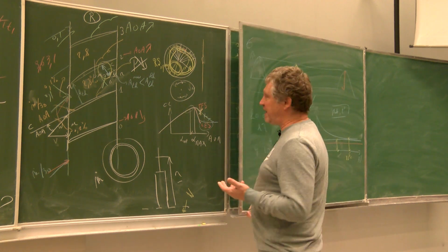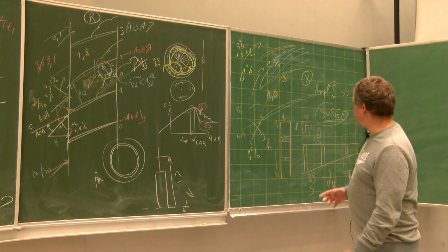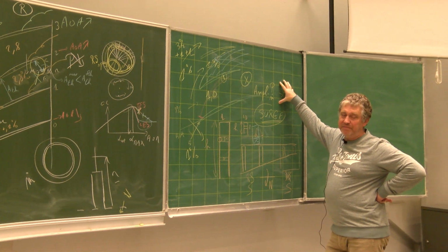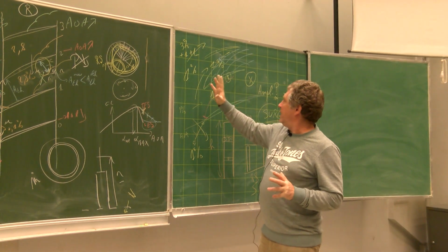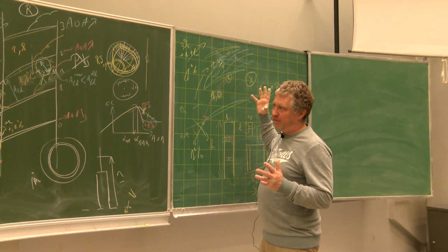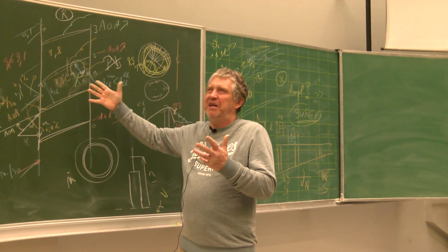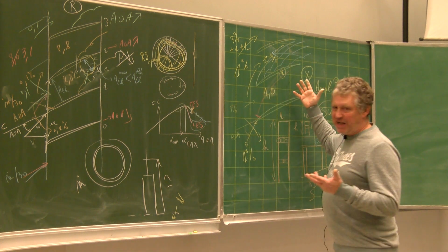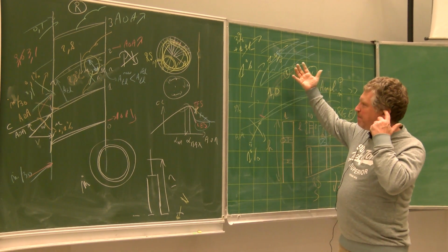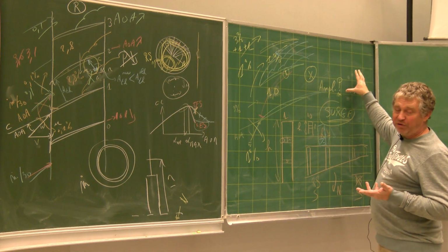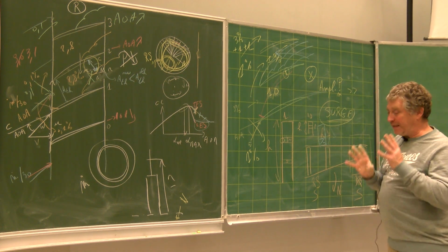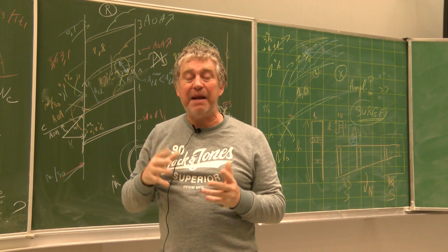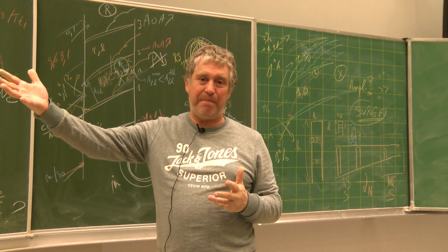What is dangerous with surge? It's mainly the combustion chamber that you have here behind. Because you see, surge is influencing the amount of m dot. Here, m dot is almost not changing. 0.1%, 0.2% is not a lot. Here, you are changing by a few percent, maybe 10%, 20%. But you are still injecting the same amount of fuel here. That means what can happen? You can increase the TIT a lot, and you can burn the turbine blades that are behind.